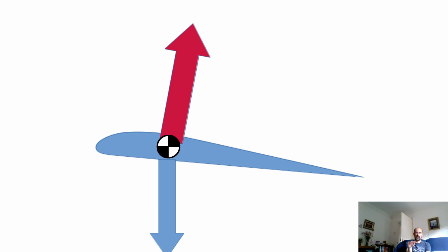And if you had a situation where the gust pushed the front down instead of up, then the opposite would happen and you'd end up going over forwards. So although if you put the centre of gravity where the centre of pressure is, you've got a static equilibrium, it balances, it's obviously not stable. So that's why we need to add something to make a wing stable.